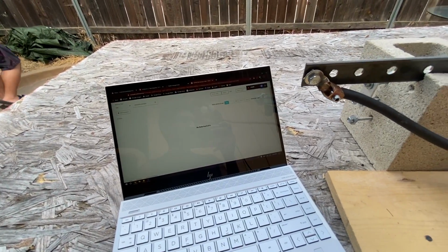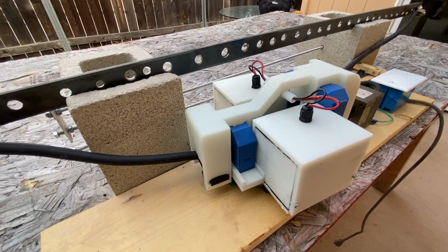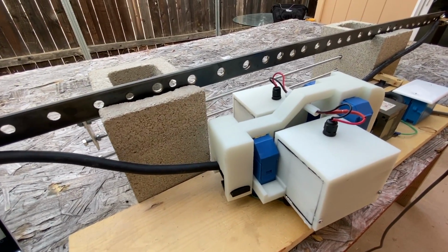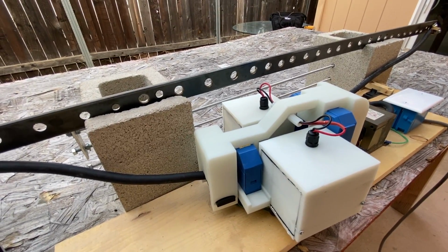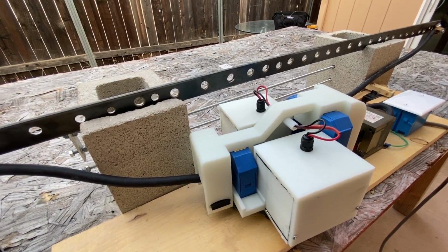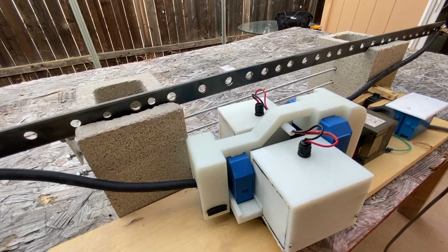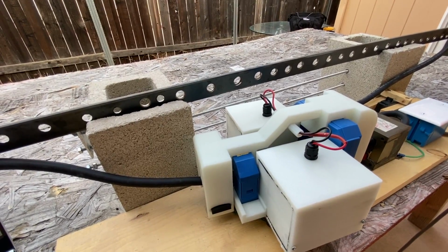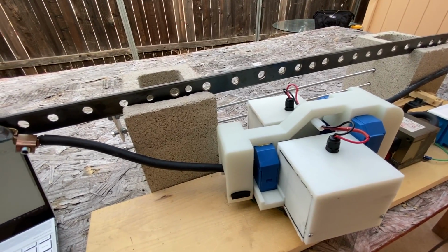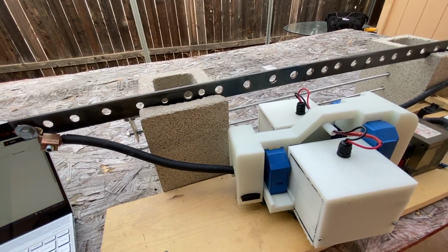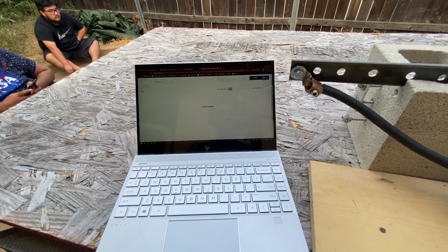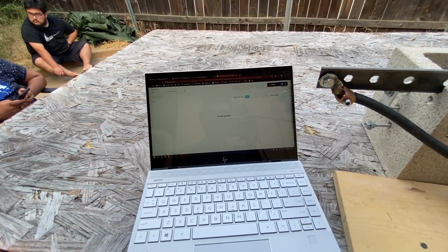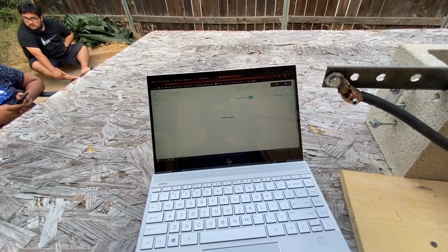And the way we do it is the device will continuously poll sensors and check for any sort of dangerous conditions. So for acceleration and for current and for humidity and things like that, if they are above or below a certain threshold, which we deem as a dangerous value, it will set a flag. And upon sending the data to the server, you'll be able to see what kind of flags were set by the system.